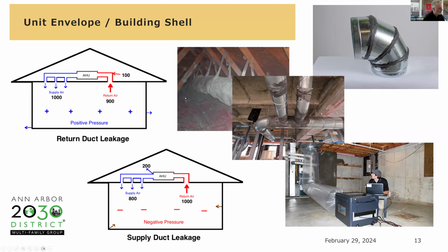And then this photo in the lower right-hand corner is called AeroSeal. They aerosolize a polymer and blow it into the duct system under pressure. It will find leaks that are in the duct system up to, I believe it's 5/8 of an inch in diameter, and it'll seal it up. And basically they just run the equipment. They're constantly monitoring the air leakage in the system. And they monitor it until they get down to whatever the target is to get the duct system sealed.